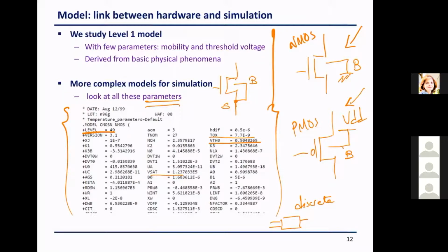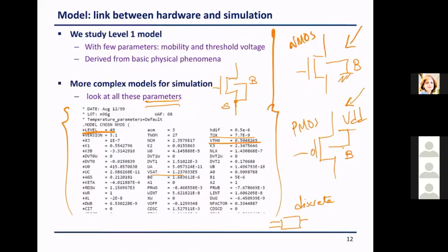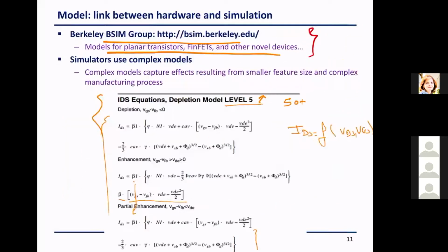They are trying to use machine learning now to see if it can replace those different levels of models that have been historically maintained by Berkeley, when we collect the data from the chip to build the models for those transistors. So this is fully empirical, and this is semi-empirical maybe. There are some characteristics that we know for sure should be included. For example, the work function, the level, the forward bias, etc. For example, VGS minus VFB.